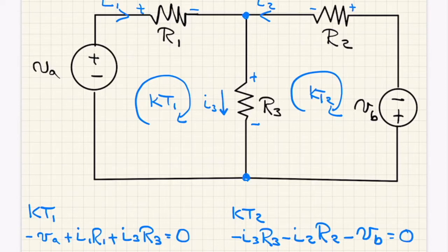That's the complete tour. Now I said I had a node to think about, so I have another node equation. Again, it doesn't really matter which way I look at it. If I take the top node, for example, then I'm going to see that the incoming currents, I1 plus I2, are going to be equal to the outgoing current, which is I3. And I'll use that equation. And so with that, I really have all the physics, the analysis of the circuit, done.